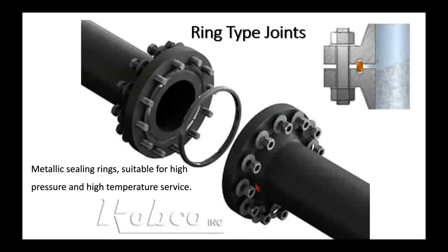So we talked about ring joints. Why are we back there again? So as for types of gaskets, we can have metallic, metal jacket, spiral wound, various non-metallic ones, so cork and rubber, pretty common. Teflon, also very common. Graphite, compressed asbestos fiber. Yes, we still see asbestos being used in gaskets.